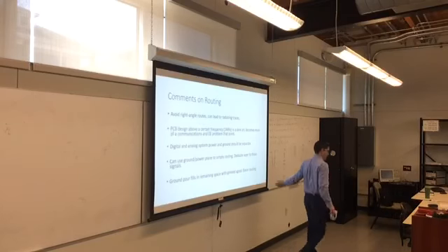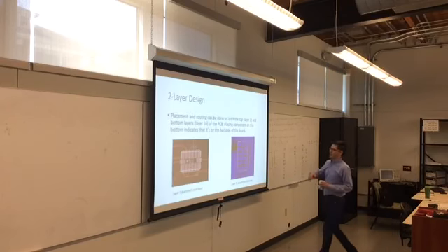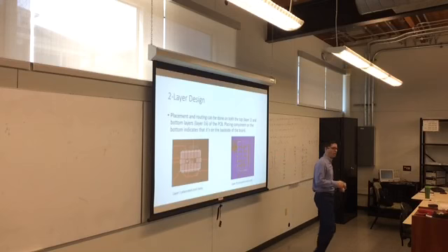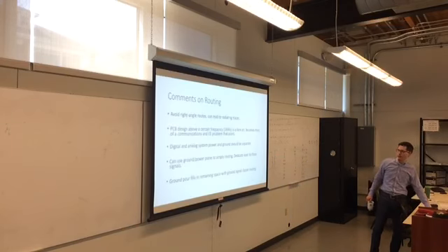As we saw in the picture back here, you can take your bottom layer, and after you've routed everything to it, you can make a ground pour and fill in it all and make it ground. It keeps things electrically quiet, and it makes the routing a little bit easier.